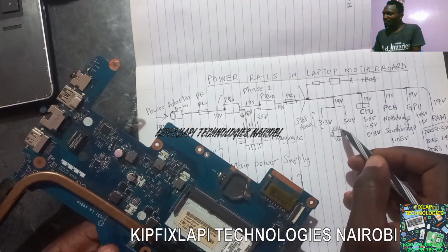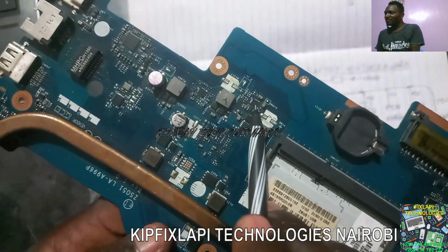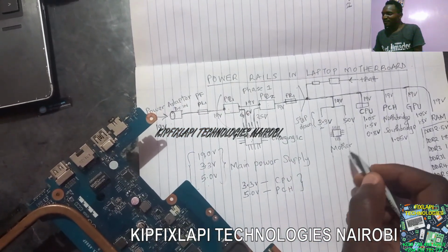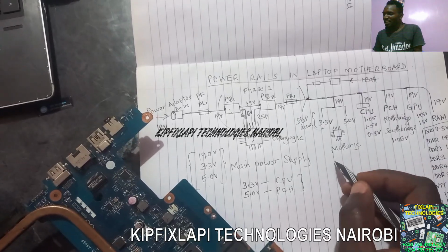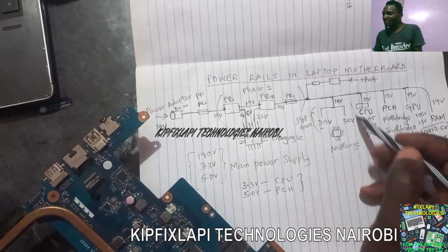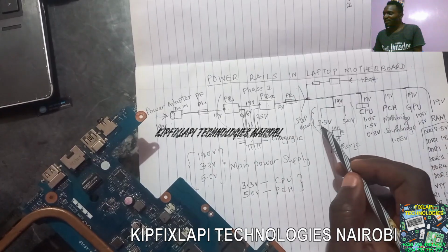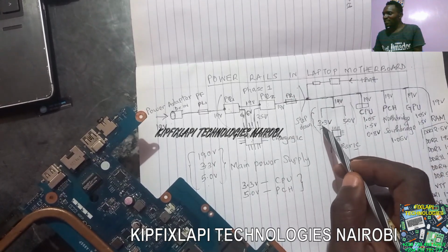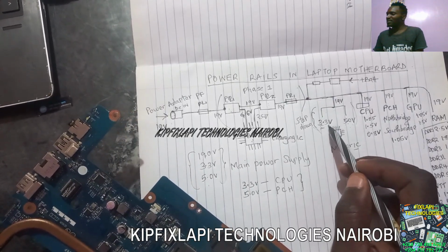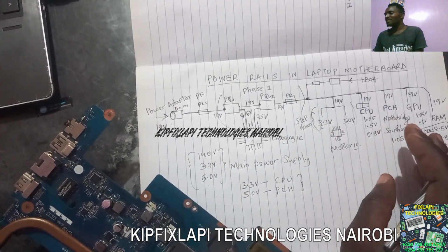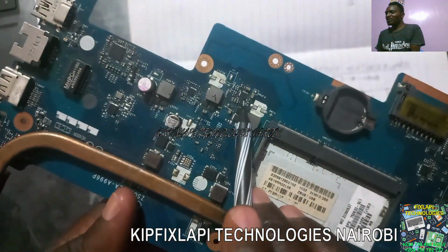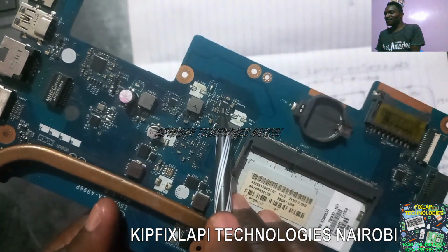And this IC, the small IC, this one, we normally call it the mother IC. Why do we call it mother? Because it is the mother of the two. So this is a family. We treat this circuit as a family. So you have 5.0 and 3.3. Both voltages must be there, right? They must be there. Without those voltages, I don't think even with breakers that motherboard would power on, right? Yes. So this is the IC I was talking about. We call it the mother IC.